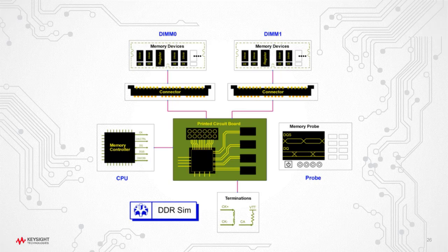Yeah, great. So for that particular part, the DDR bus simulator is a statistical simulation. When we start to talk about what's going to be needed for DDR5, then inside the equalization you can expect things like a variable gain amplifier that might need to be adjusted, and also some other aspects of how the DFE or an interpolator on the sampling instant might adjust.